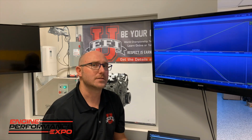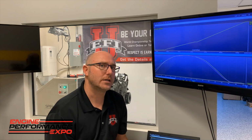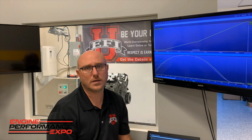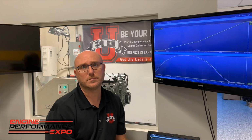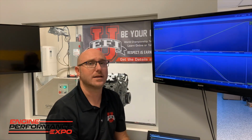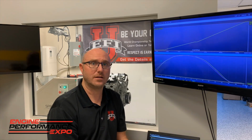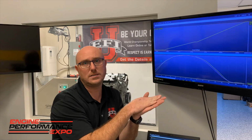So let's think about that for a second. Let's say a really stout race camshaft, maybe you look at your cam card and it says the intake valve opens 20 degrees before top dead center, and it closes 60 degrees after bottom dead center. So now you think about that piston, which was at bottom dead center, it's some distance up the bore by the time you've got 60 degrees past bottom dead center. Well, what we just saw is that it's bouncing for another 40 degrees. So that means I'm really 100 degrees after bottom dead center before I'm totally sealed in that cylinder.